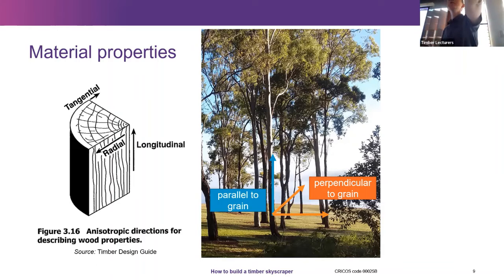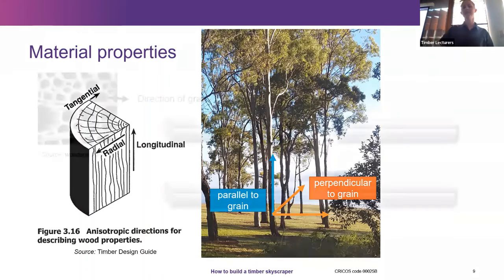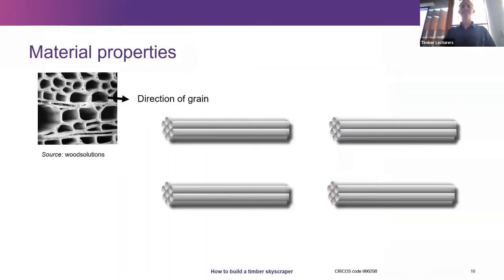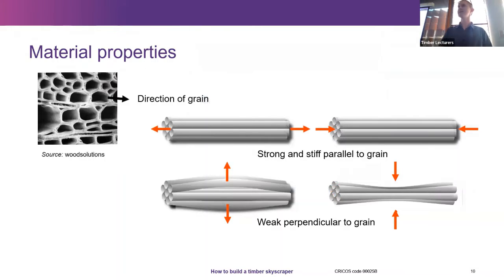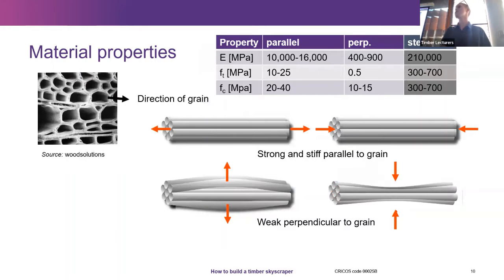And if you look at the table here in the front, I mean, it's a veneer. It's made to look like solid timber, but it's not. But that would be the grain direction here in the front table. There we go. That's the straw analogy. So strong and stiff parallel to the grain, but pretty weak perpendicular to the grain. So that makes it just a little bit more interesting to design this timber and apply it to its strengths.